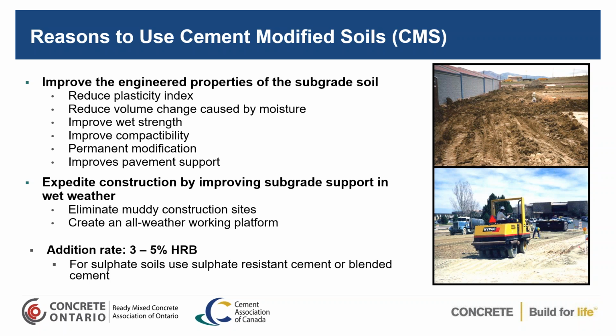Now, when you're doing this, you have to realize that the resilient modulus of your subgrade does change, but it only changes to the depth that you do your stabilization, which is usually 300 to 400 millimeters. So what you want to do when you're doing your analysis is consider if the material is deeper than that, you want to look at doing a blended resilient modulus value so that you don't use too high of a value when you're doing your analysis in pavement design.